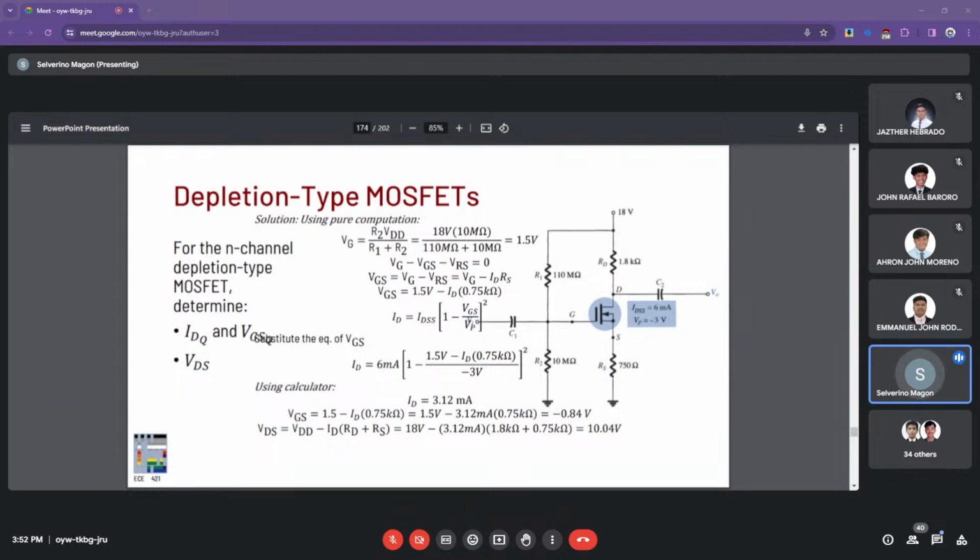We have the VG figures. No, okay, so VG on the other hand is maintained at 1.5 for the first calculation. So meaning in the off condition, you can always measure 1.5 volts also on this side.